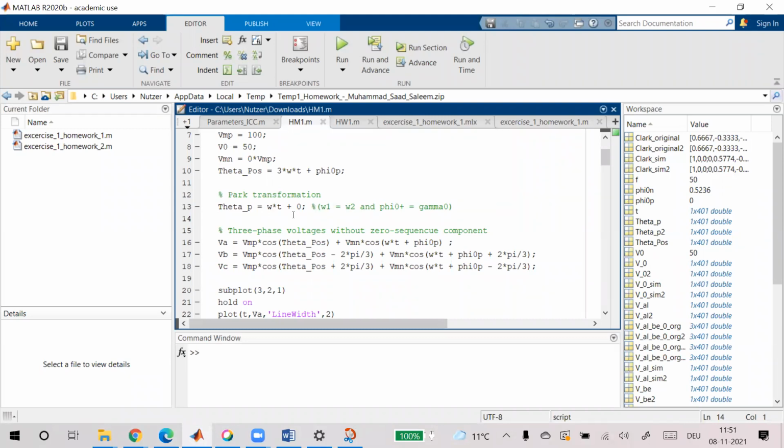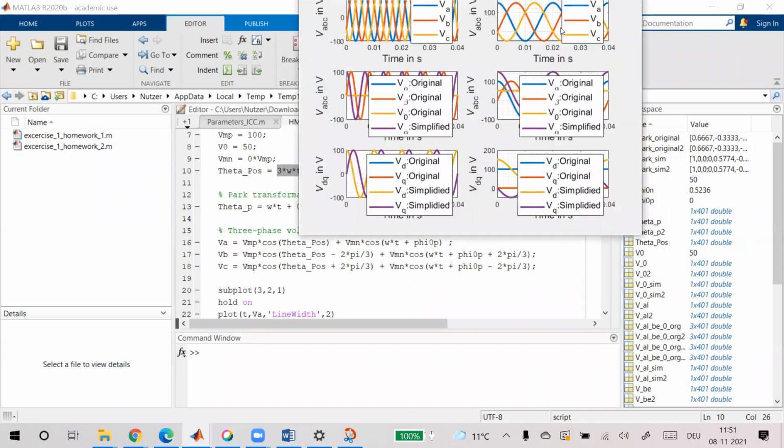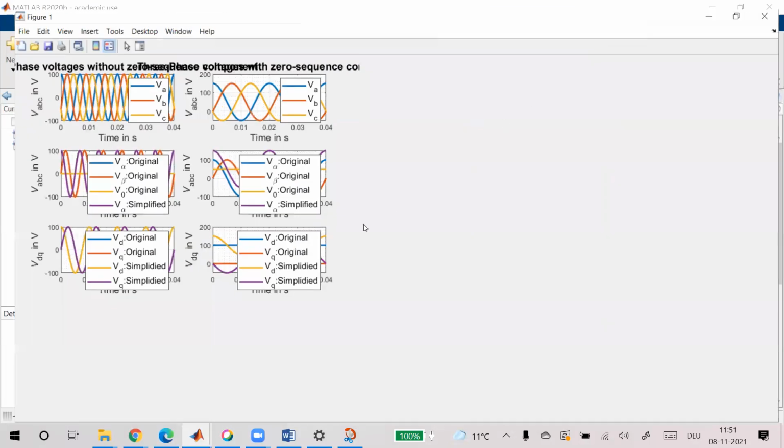There's no negative sequence, and the park transformation frequency is same as fundamental, but we are doing transformation for third order harmonics. AC. Only AC. And what would be the frequency? 2 times. Yeah. So that's 100 hertz. For our case, it is 100 hertz. So you would see only AC, and you would see frequency as 100 hertz.